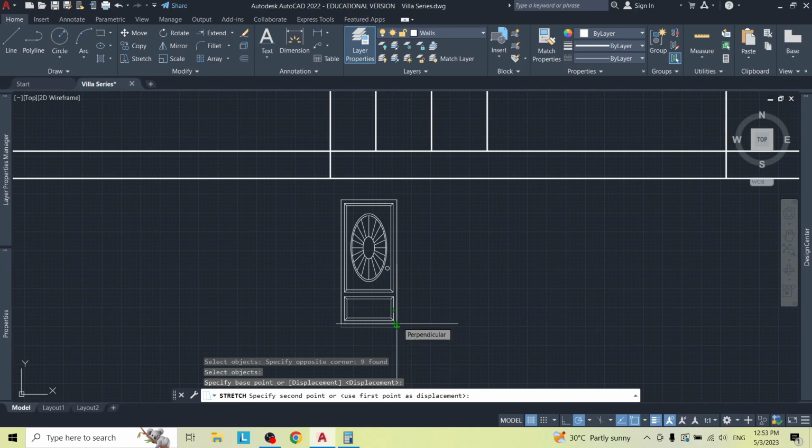And remember, the height of the door is 2101, but the height for the space is supposed to be 2000 millimeters flat. So that means it's 101 millimeters too tall.